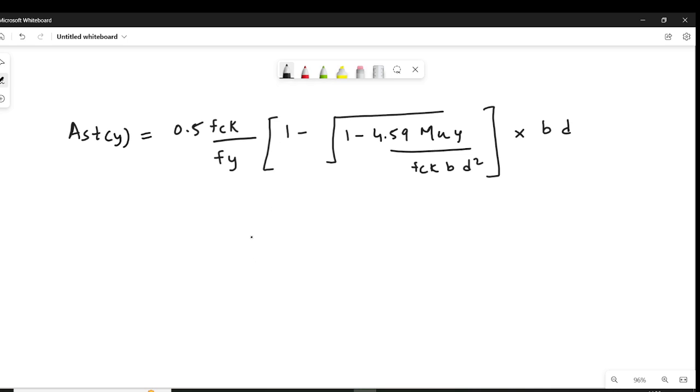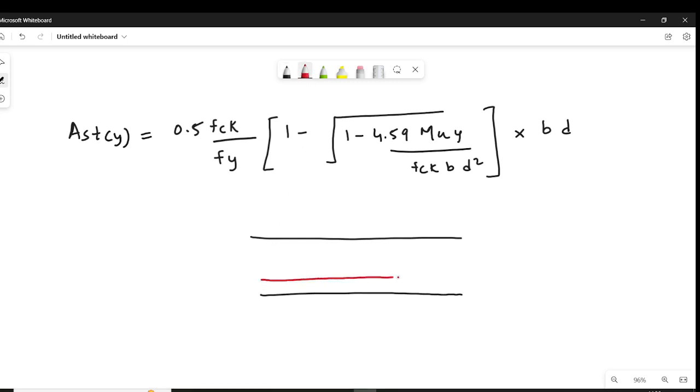So you see, this is the footing in the x direction, and this is the reinforcement that we have calculated, which is in the x direction. So this D we know, and this D is associated with the reinforcement in the x direction. D is the effective depth. It's the distance from the top, from this point, to the center of the reinforcement.